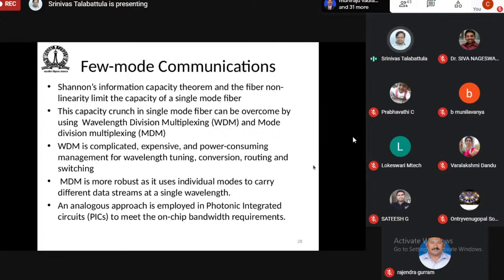In optical fiber communication, many of you know that we use a single mode optical fiber. Only one mode is supported by the fiber from one point to the other. This is because if you have multiple modes, you have a problem, and it's very difficult to retrieve the information and so on and so forth. A lot of problems are there due to dispersion. Of course, there are a lot of other problems in communications, like loss in the attenuation of the signal. Many things are interrelated, like crosstalk and so on will come through. So we use single mode communication in optical communication.